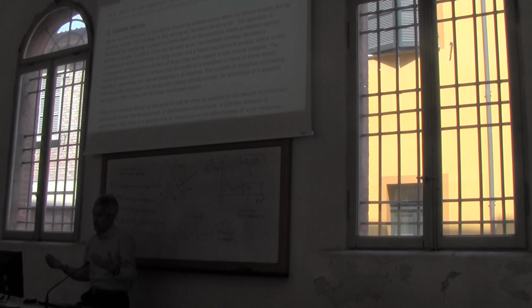During high storms you have a lot of sediment transport, and this is why the dune is so elevated. And the dune may be formed by the sand that is taken from the berm. While the berm is something seasonal, the dune is more permanent, and being elevated can host vegetation. As we said, it's vegetation that is resistant to salted spray, but there is some vegetation because there is fresh water, because it's elevated. So there is storage of water during rainfall, and so the plants can survive.